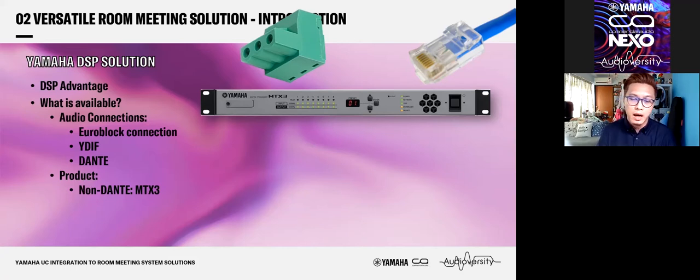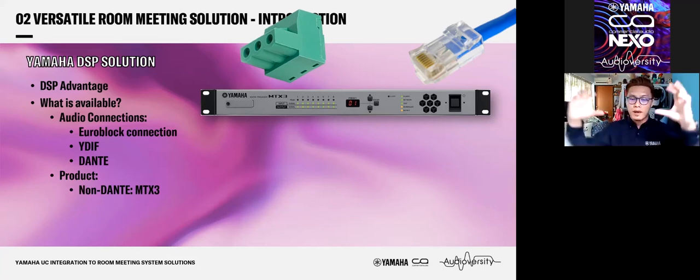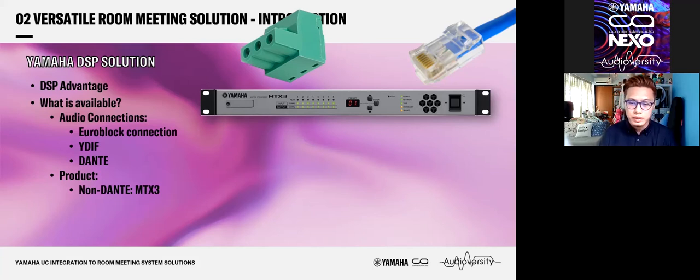It's surprising to see how small DSPs are nowadays, saving rack space and able to clamp down so many features, unlike in the past where EQ on the output stage and the input stage, you had individual processors for each function: feedback being one function, matrix maybe a matrix switcher, and also output processing EQ, or any other features is all squeezed digitally into the DSP.